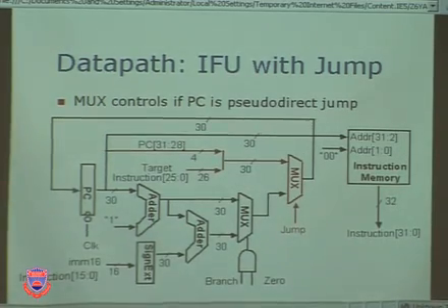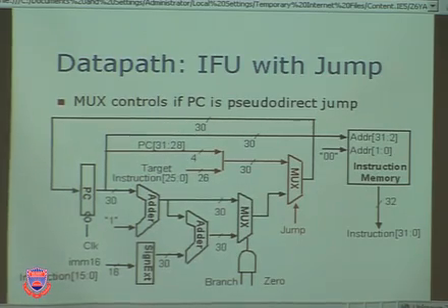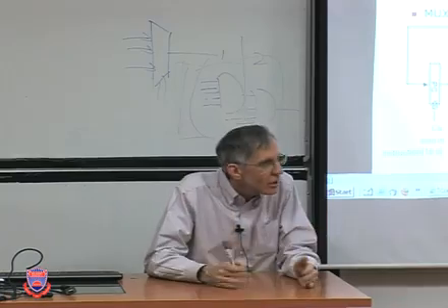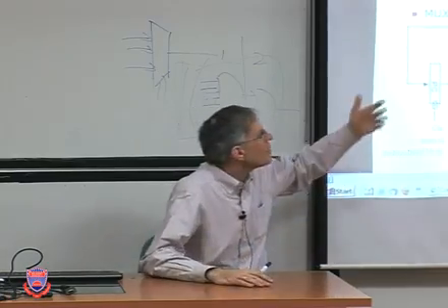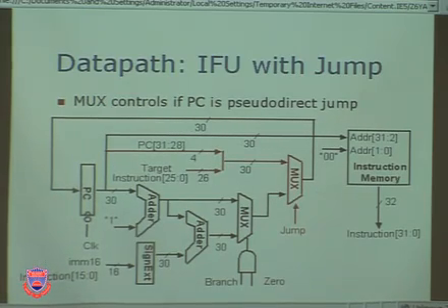To speed it up. If instruction fetch was on the critical path, and it was part of keeping the computer slow, you would speed it up. But if instruction fetch was already plenty fast and the problem was in the data path, and you had slow ALU and slow register fetch, then you would say, why am I wasting my time on this? I want to make the slowest case faster because it's on the critical path. So obviously you would use your engineering manpower wisely to know where to invest it for speed up. But I see some good candidates for speed up right here. We've already shrunk the size down by making everything 30 bits instead of 32. That was a big savings.